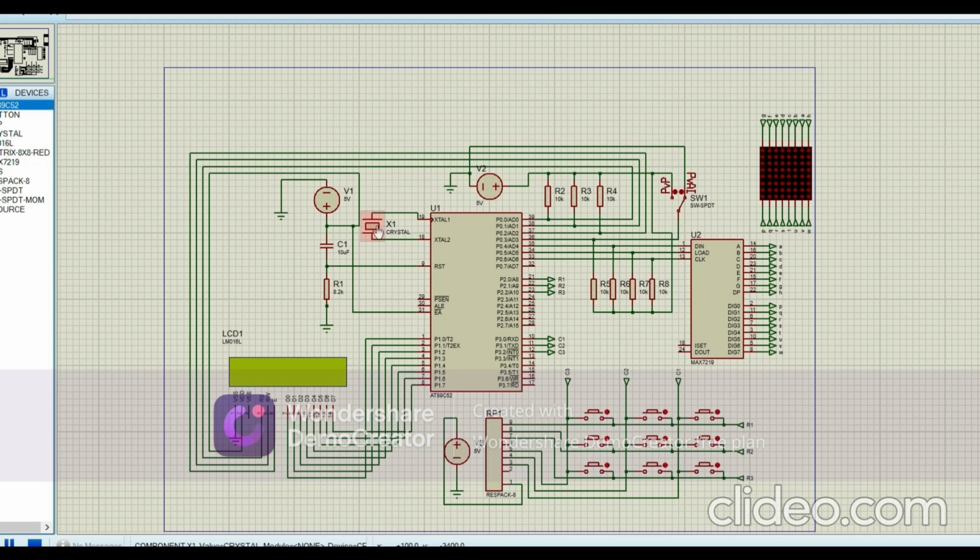For input unit, a 3x3 push button keypad is used. We chose individual push buttons over a matrix keypad or joystick because direct mapping gives the best user experience. A child or adult can press exactly the cell they want without confusion.